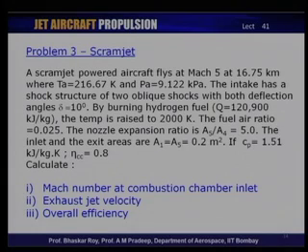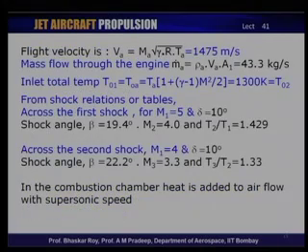What we will do is, we will find the exhaust velocity and then find the thrust and the SFC, and we will find the propulsive efficiency as we have done before for comparison of the various jet engines. The flight velocity for this particular craft can be now computed from the given Mach number, which is 5, and that comes out to be 1475 meters per second. Mass flow through this engine, again using the continuity as before, we can find 43.3 kilograms